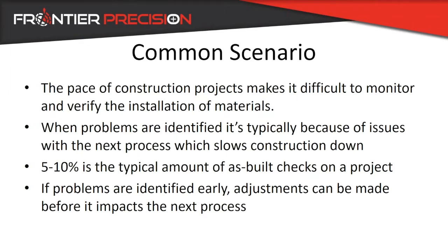And typically you recognize the problem when the next part of the construction workflow actually tries to take place. If you are trying to set steel on top of an anchor bolt and the anchor bolts are positioned wrong, you typically don't find out until the steel doesn't fit. When that happens, you're in a very difficult spot because now you're slowing down the construction process. Your schedule gets behind, everything falls back, and you're at a standstill until the issue gets addressed.